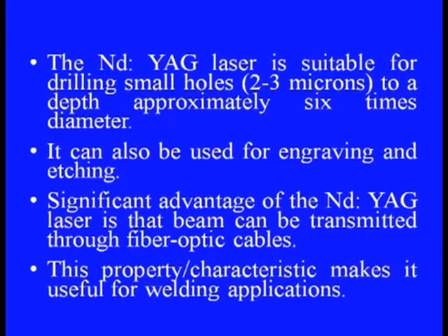A significant advantage of the neodymium yttrium aluminum garnet laser is that the beam can be transmitted through fiber optic cables. This property or characteristic of this laser makes it popular for welding applications. Now, let us see how the material removal or cutting takes place using a laser beam.